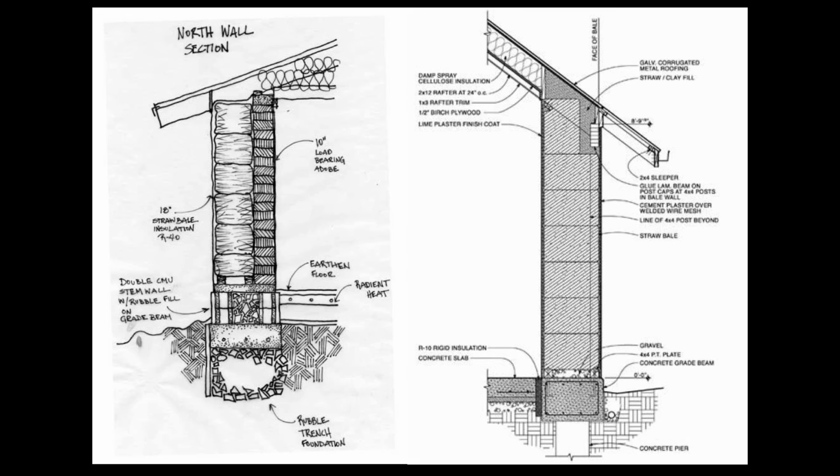Hatching has a lot of value in communicating these materials and structural details in both sketching and in final digital drawings, and is able to communicate very complex detail and information. When applying hatching, please consult something like the Architect's Pocket Guide or other architectural drawing aids or drafting books. It's important to remember that hatching is a language and not a made-up pattern.